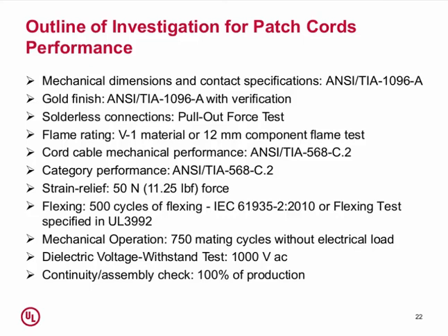Although it's not a bad idea for manufacturers to go through the IEC documents and go through the entire program when they're designing plugs for this use, we decided that we would use a pull-out force test that's in that specification. Assuming that there has been work done on the connection aspect already, this pull-out force test verifies that the connections are solid, that the connections are appropriate for the type of cabling that's being used.